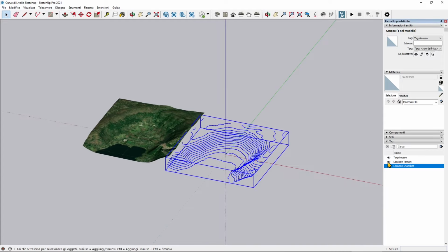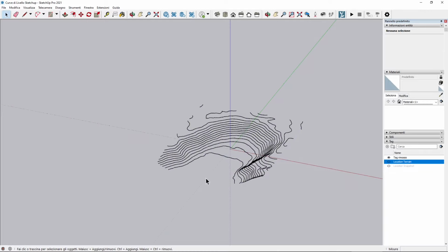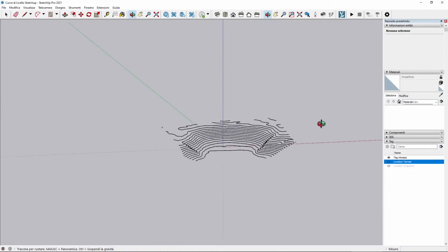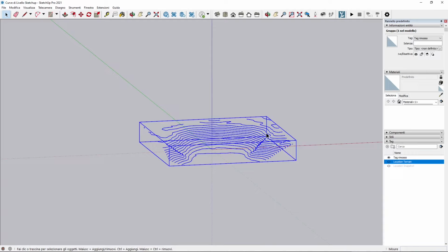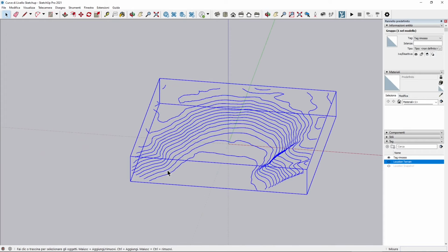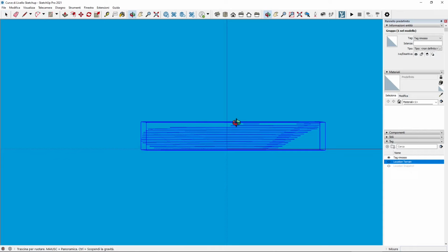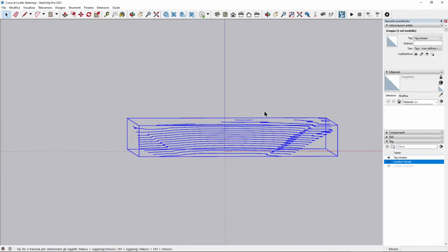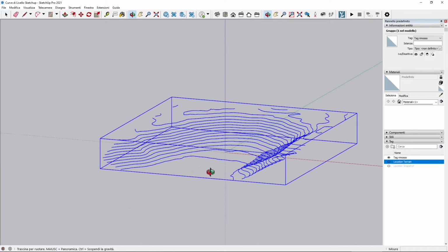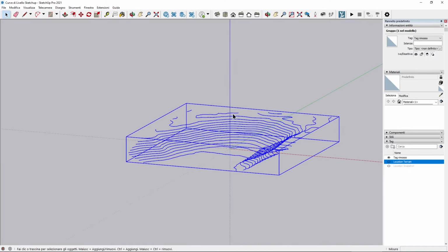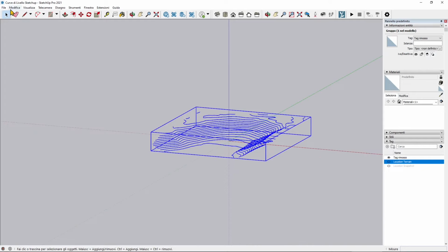So I'm just going to show you that this is what we need in Revit to make it work. And these are actually 2D lines or 2D curves. So they are vector graphics. They have segments and vertices inside, and you can see they are displaced in the z-axis. So you can see that these curves are not in the same plane, but each one of these has a different height to represent again this hill or a mountain or whatever. So this is what I need to export.